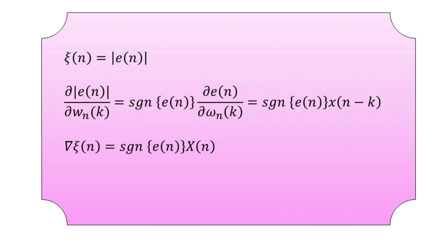So this was the example where we have made use of the error signal with the help of the signum or the sign of the error here. Now in order to reduce the computational complexity, we have one simplified way of using the sign of the data signal also.